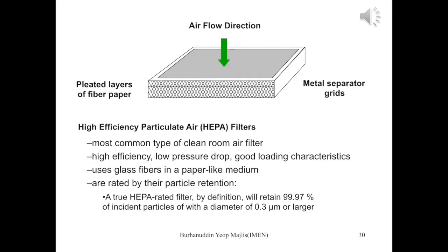Okay, this slide shows the HEPA filter, where you can see the airflow direction from top to down. Now, because we need a high pressure to push the airflow through the filter, we now have one filter with a fan already built in, so we call it a fan filter unit.